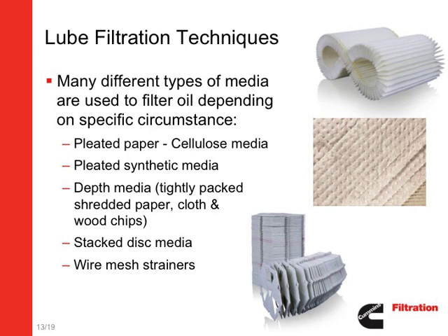Pleated synthetic media can be made from glass or various polymers. Depth media is tightly packed shredded paper, cloth, and wood chips. The densely packed organic materials filter not only the solid particulates, including catalyst fines, but semi-solids, petroleum gums, asphaltenes, and other organic compounds through absorption by the depth media, which acts more like a sponge for contaminants rather than a screen to capture them, as in a cellulose filter.